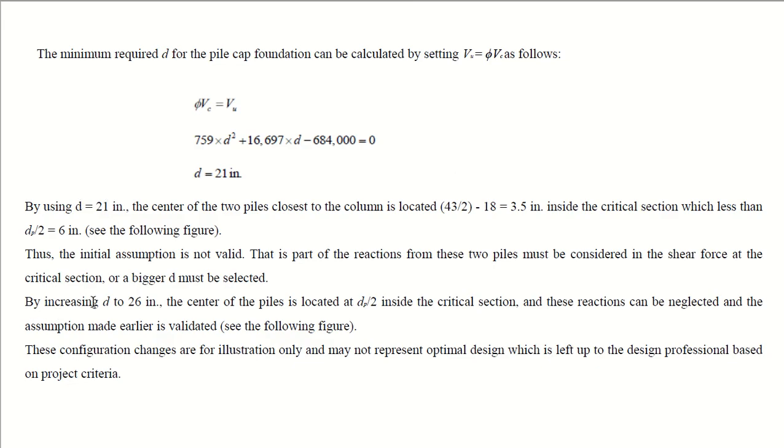It says if you increase D to 26 inches, then the center of the piles is located at dp by 2 inside the critical section. And these reactions can be neglected and the assumption made earlier is validated. These configuration changes are for illustration only for the students and may not represent optimal design.